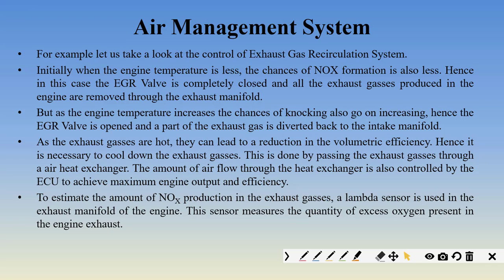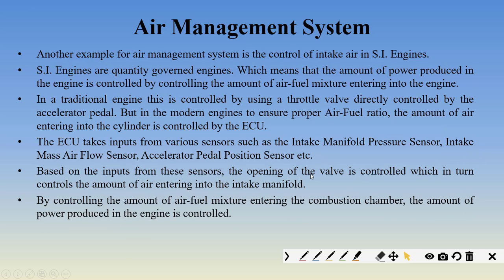These all sensors will collect data and send it to the ECU. ECU, based on the data collected by these sensors and the program written inside it, will control that valve. The valve which I was drawing over here, that is known as the EGR valve. So this is how they will use it to control the NOx production.